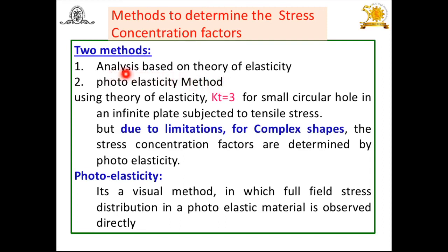By using the analytical method based on the theory of elasticity, suppose a rectangular plate has a circular hole and is subjected to a tensile force, which was shown in an earlier slide. You will get KT, that is the stress concentration factor, equal to 3, but in this case for a small circular hole.